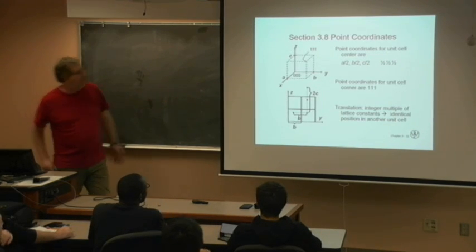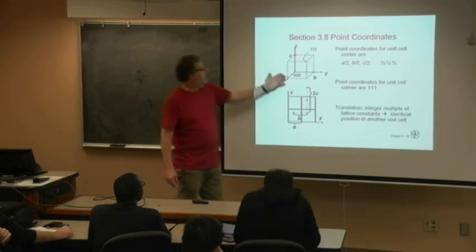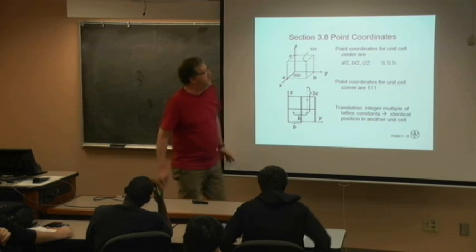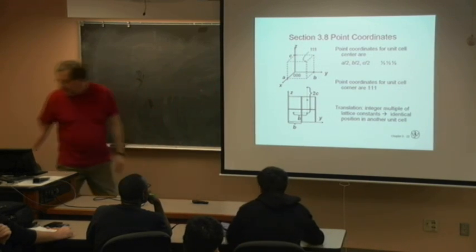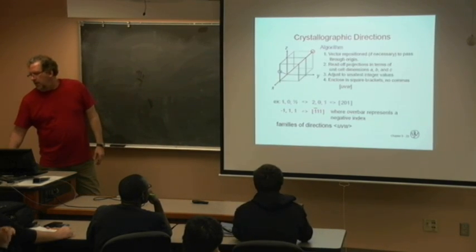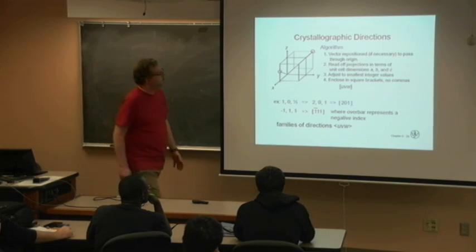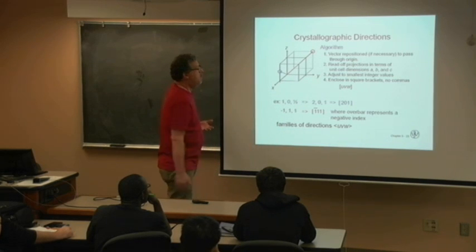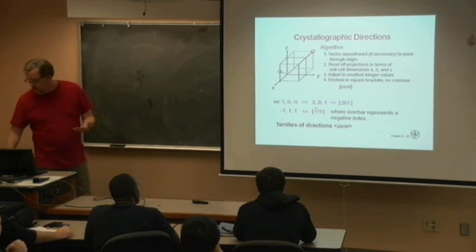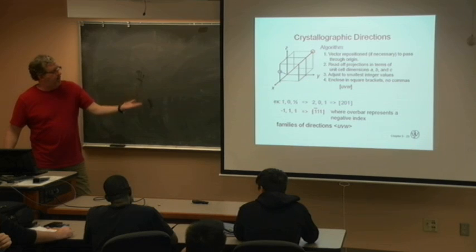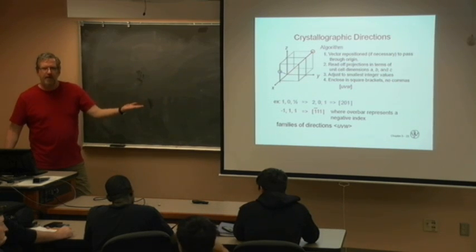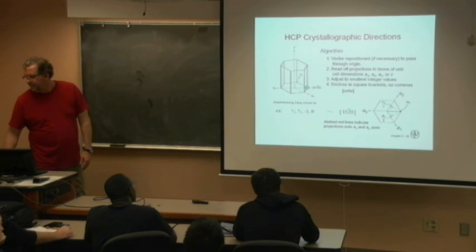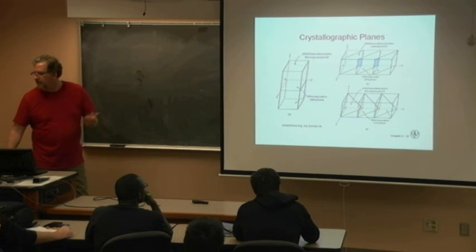Understand it. I'm not going to say draw a 111 point or so forth. Those are not the kind of questions I go after. The crystallographic directions and so forth, I think you should know that because it relates to when I want to make a device. It relates to whether I process my wafer right side up or upside down, perhaps even. And so we've got all those crystallographic directions.